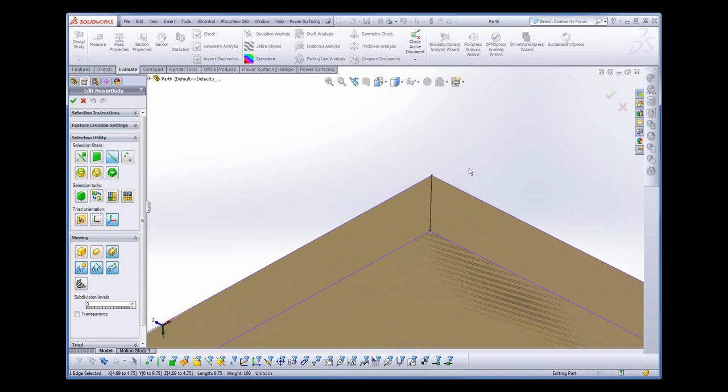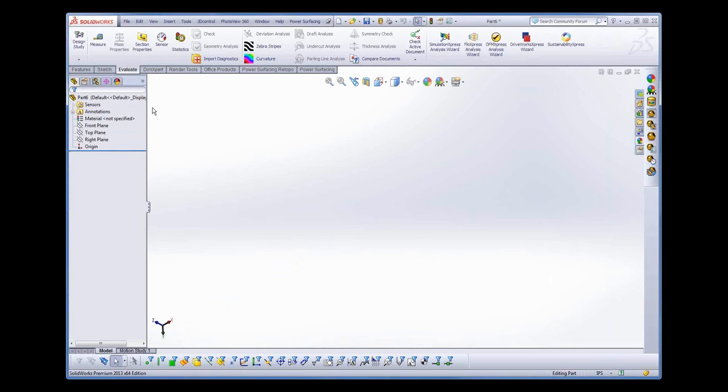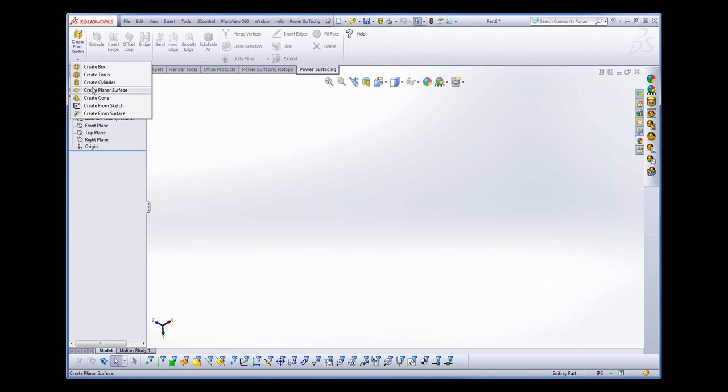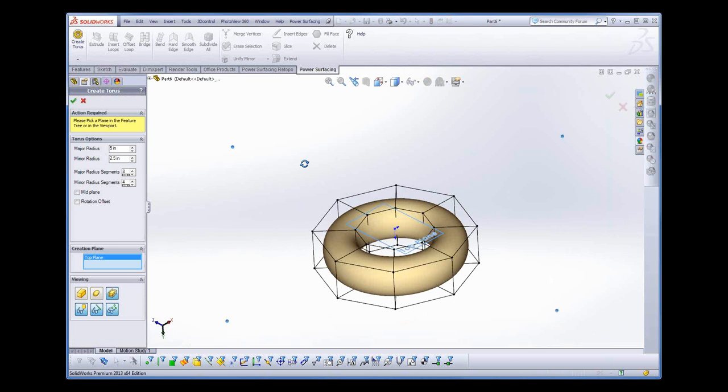What are some general thoughts, strategies about how to begin from sketches, primitives, what shape primitives for what final shapes, etc.? Well, it's one of those things that you probably have to play around with to get a good idea. For example, you can actually create almost anything starting with a box. Sometimes it's more convenient to create other shapes just to get you closer to where you want to get without as much effort. The one I find most useful is the torus. Yeah, torus is good for making rings and things like that. It's kind of hard to create a torus shape just from a box and get everything nice and uniform.